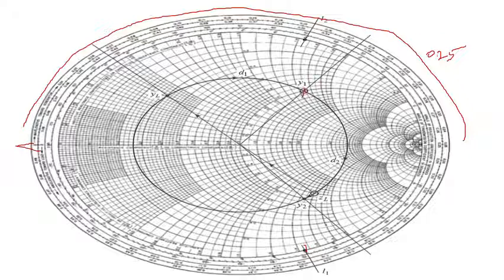What 0.097 designates is that the total distance is 0.347 lambda. This 0.347 lambda subtracted by that 0.25 lambda, you get the value as 0.097 lambda. Please note, if you cannot remember this, just remember that if this value is greater than 0.25 lambda, we need to subtract. What happens if it is less than 0.25 lambda? We will check it out.